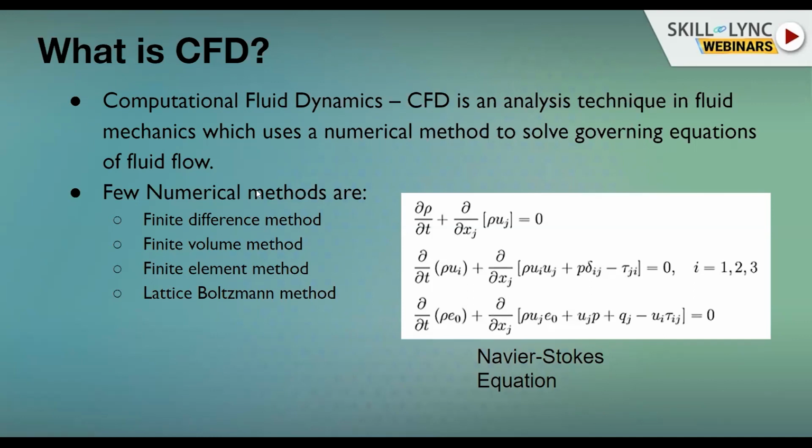Nowadays it is mostly the finite volume method. That's what is used in many commercial softwares, and it has become a kind of standard. The finite difference method is what you find in a lot of textbooks as well, and that is where it started. In the finite difference method, we solve the differential form of the Navier-Stokes equation. And in the finite volume or the finite element method, we solve the integral form of these equations, not the differential one. A lot of advantages are there in the finite volume method, which satisfies the conservations, and we can capture the shocks exactly.